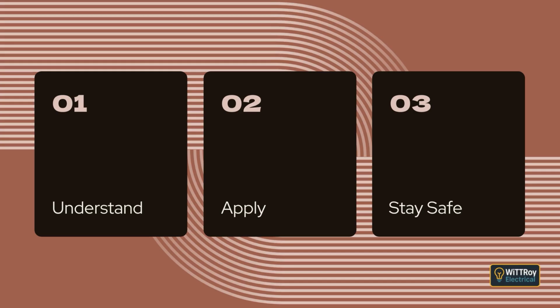Where a switchboard has 2 doors, those doors should be spaced well apart. If a switchboard is in a narrow space, the door must be able to be fixed in the open position so that workers are not pushed toward live parts. There is one exception. These special door and emergency exit rules do not apply to small domestic electrical installations.